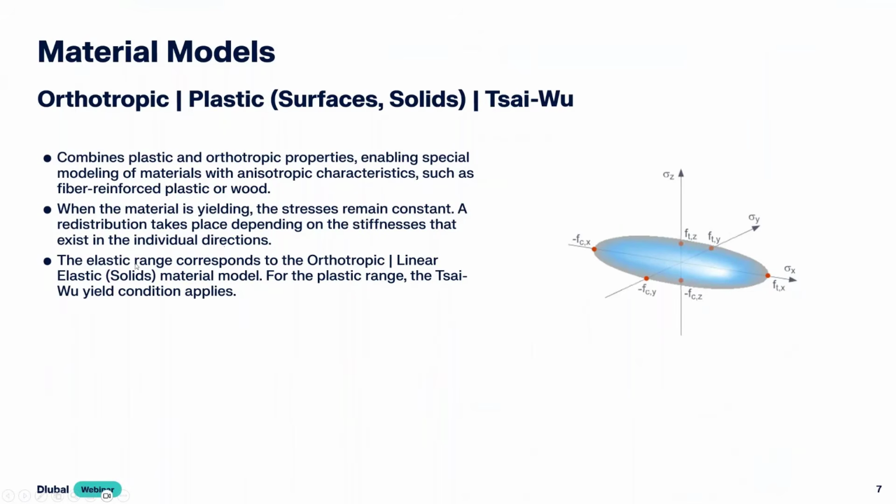It's also important that the elastic range corresponds to the orthotropic linear elastic material model, and for the plastic range, the Tsai-Wu yield condition applies.